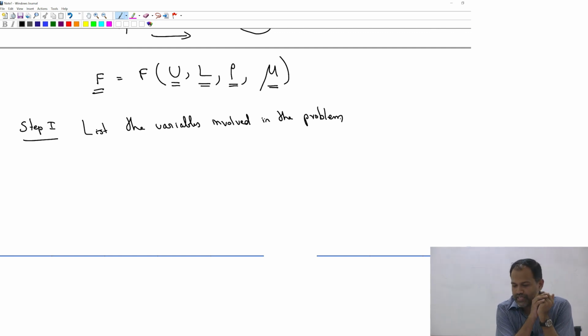So in this particular problem, I said, okay, we know that the speed with which the fluid is coming can be an important parameter. The size of the object, it does look like it can be an important parameter. I did not say, for example, the thermal conductivity of the fluid is important, because one wouldn't expect that. I did not say the surface tension is important, because there is no real surface involved. Okay, so you should not select too many parameters, because then it's not going to give you any simplification. The thing that you should really look for is what could be the relevant parameters. You could keep adding to this later and see whether things are different or not.